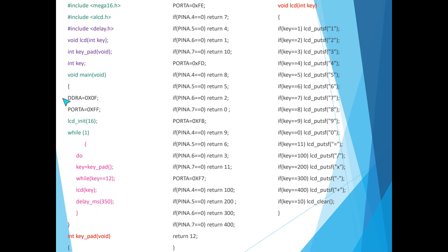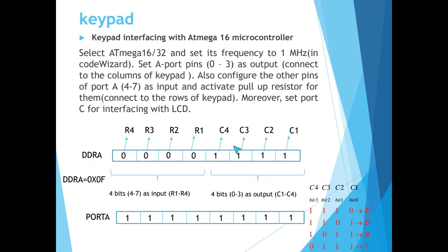I said that at first we configure the port A pins. First 4 bits are configured as output, and the other bits are configured as input.